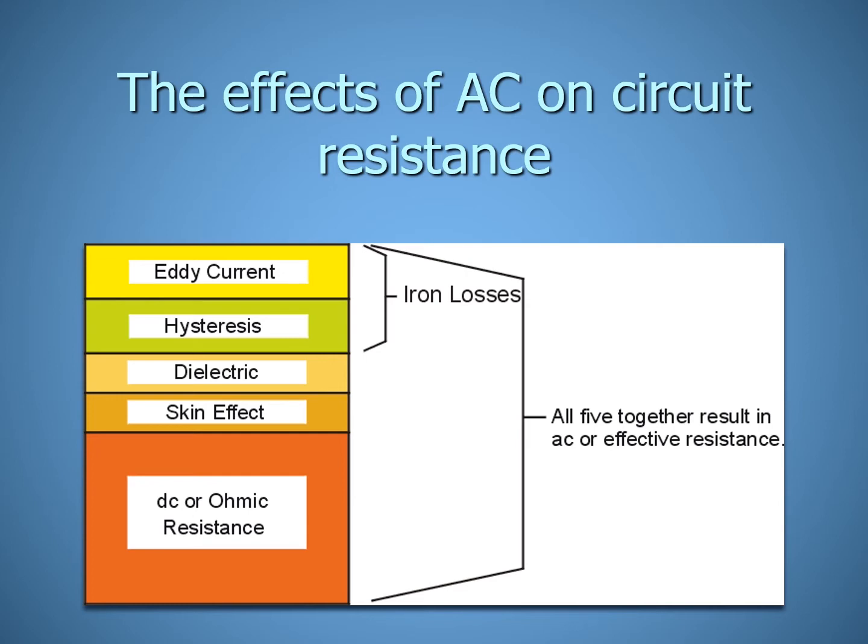First, let's talk a little bit about the difference between AC and DC resistance. If you were to take a coil and put an ohm meter on it, you'd get an ohm value back. That ohm value is based on the physical resistance, therefore just the resistance and not the impedance or anything else of that coil. That's also referred to as the DC ohmic value.